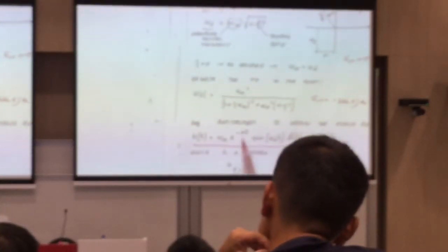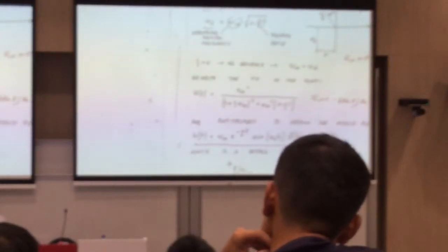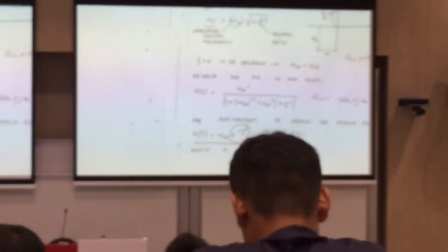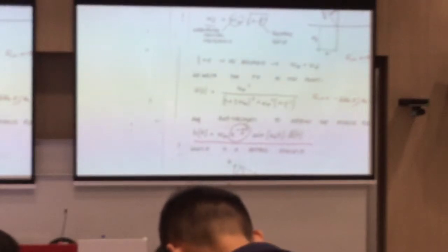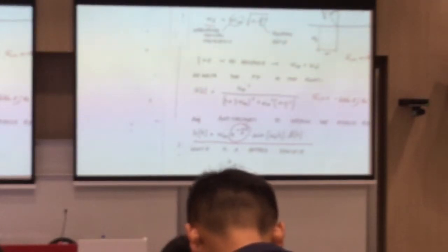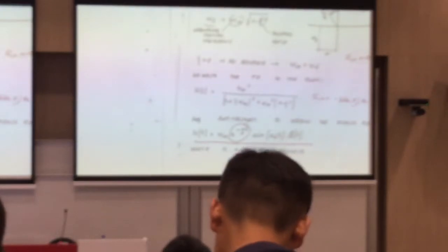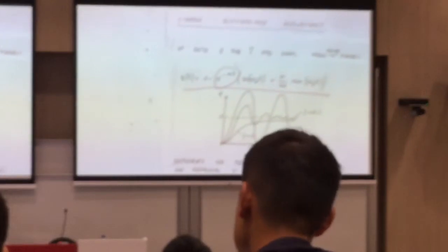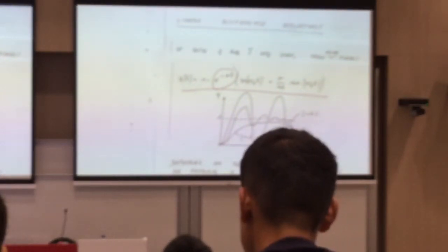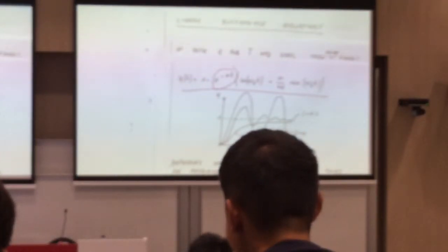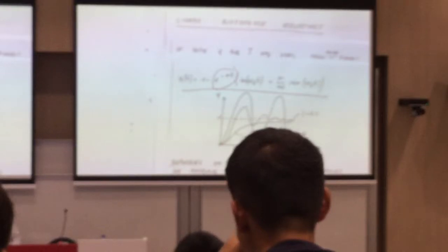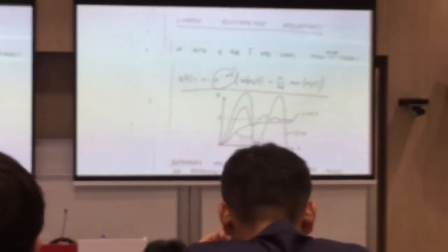So which one determines the stability? It is this sigma, this part. When the damping is such that your impulse response decays to 0, then your system is stable. Your impulse response eventually will decay to 0, and if this decays to 0, then your unit step will converge to the steady value. So through this, you should understand what stability really means, rather than just remembering it by heart.